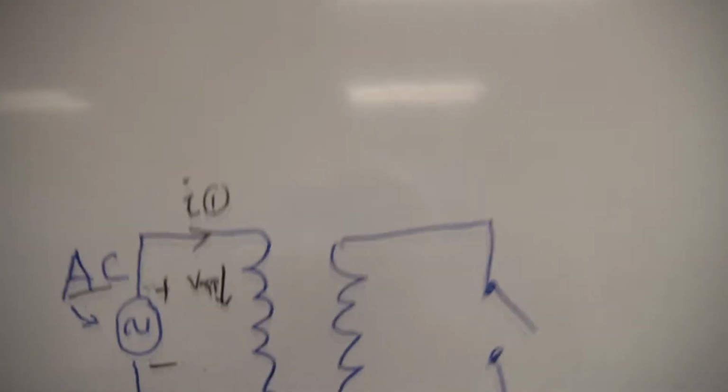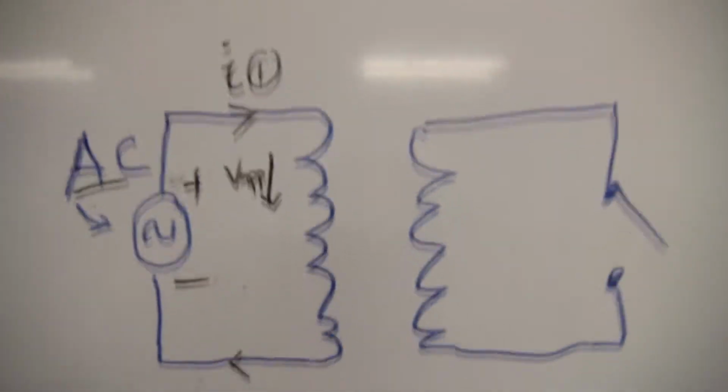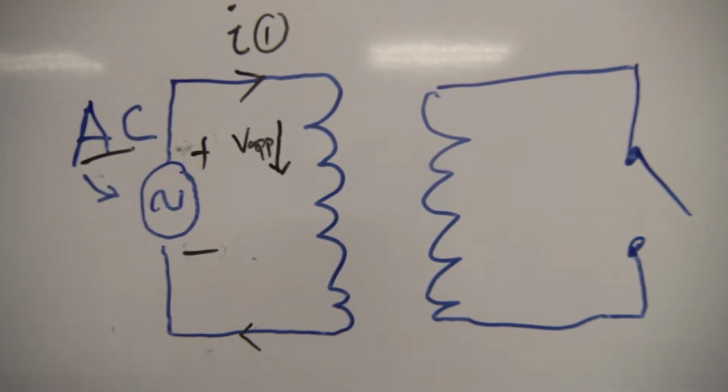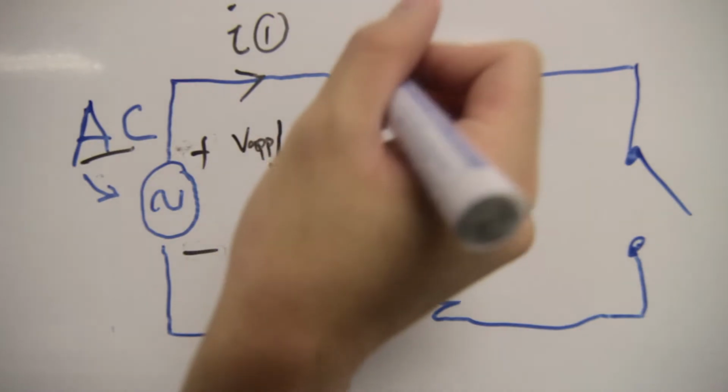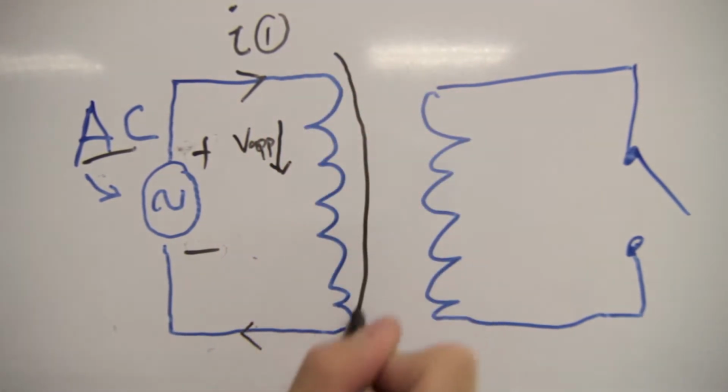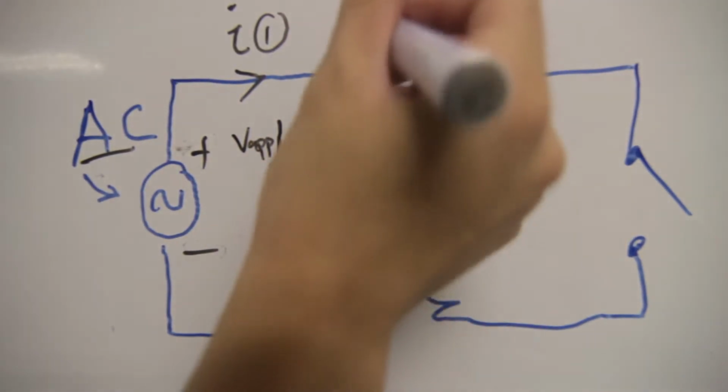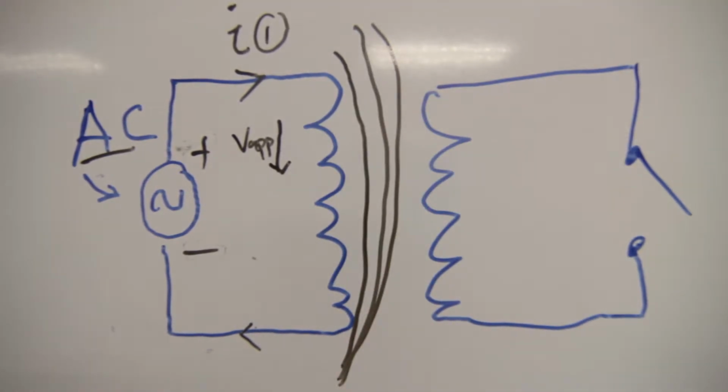So let's get back to my beautiful drawing over here. Like what Ming Hui said just now, how a transformer generator works is that the current in the primary coil will produce magnetic flux that goes through the secondary coil, and therefore there will be induced EMF in the secondary circuit. But in this case, the secondary circuit is open, therefore there will be no current.